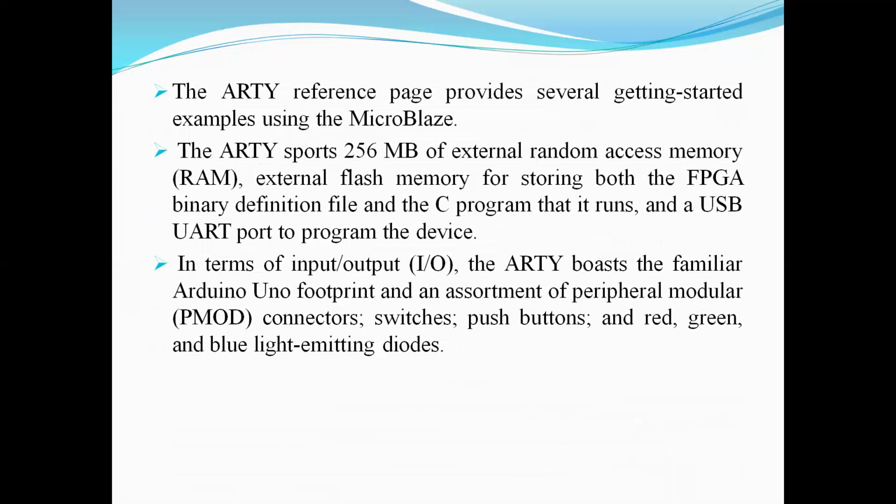The Arty reference page provides several getting started examples using the MicroBlaze. The Arty supports 256 MB of external random access memory, that is RAM, external flash memory for storing both the FPGA binary definition file and the C program it runs, and a USB port to program the device.